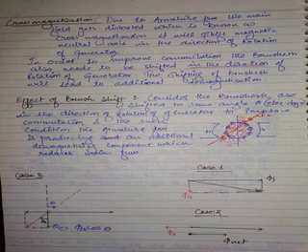If theta is 0, what is the demagnetizing component? 0. So the problem starts with theta. Is the point clear or not? So that's the reason why brush shifting is not done now, but that's the oldest method to improve the commutation.